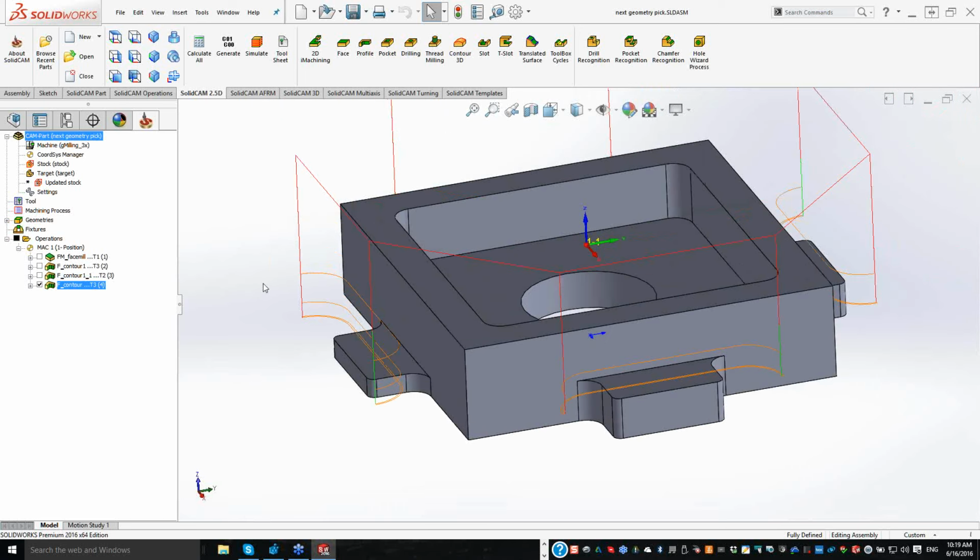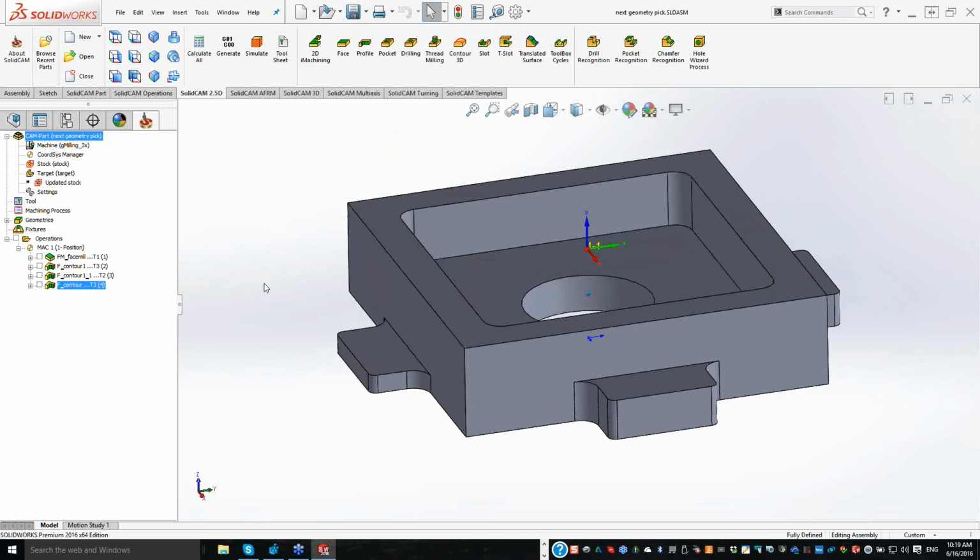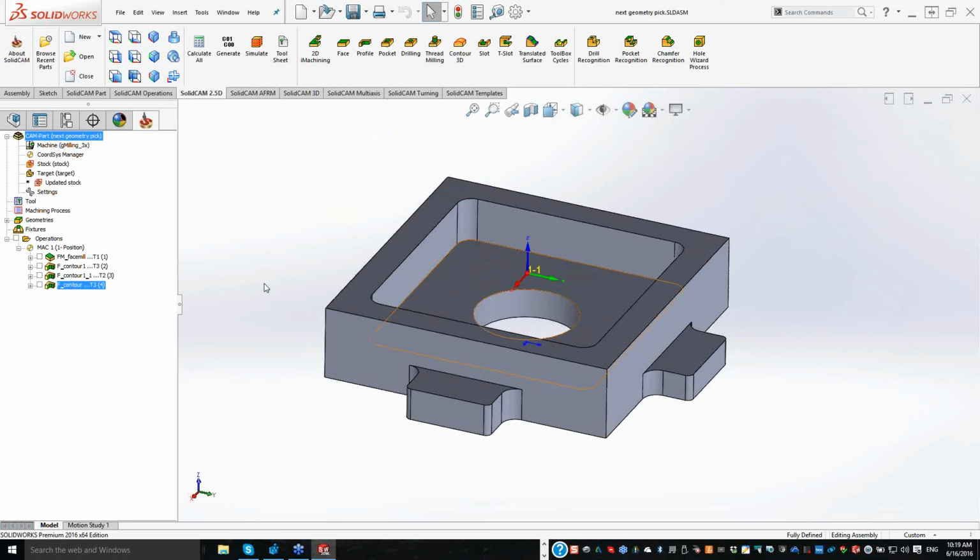Now, to finish this off, I'd like to work inside this pocket. I want to go over one of the things that Anthony did in last week's webinar on iMachining 2D. And I'd like to actually machine out this area over here. Now, note I have a hole over here. I'm going to first do a drill operation. The first time I'm going to do a drill operation, I'm going to go all the way through the hole. Okay? So I'll do a simple drilling operation for now.